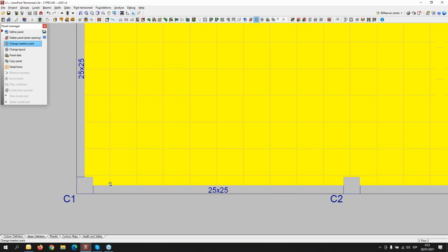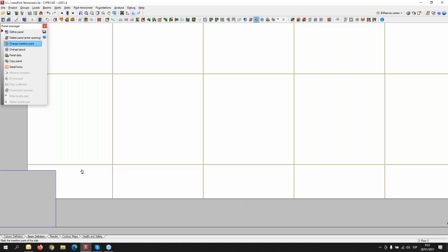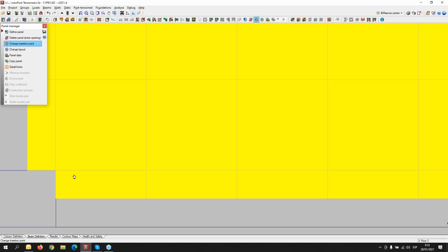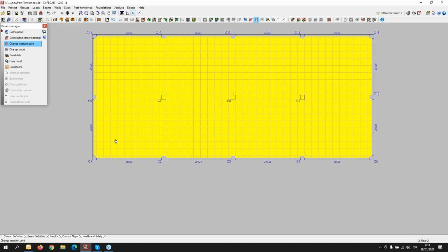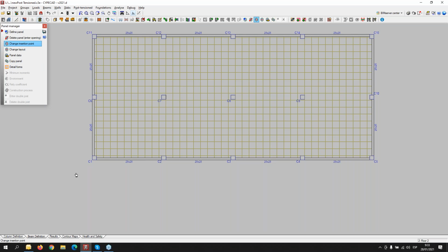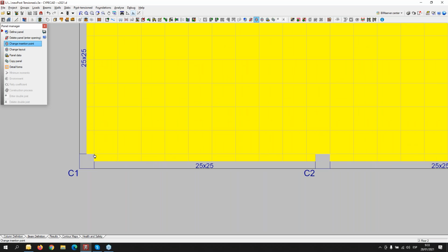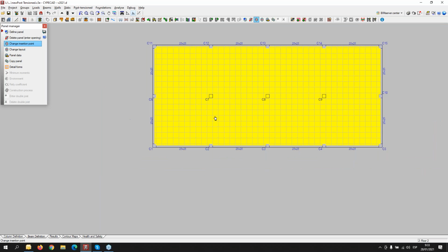In this case, we will take this point and redefine its position in order to define the tendons in an easy way, and this point can be applied, for example, in the reality of the project to take into account the position of the ribs to apply the reinforcement.